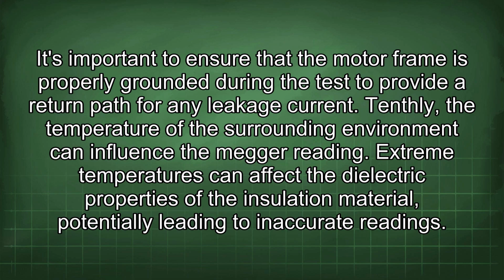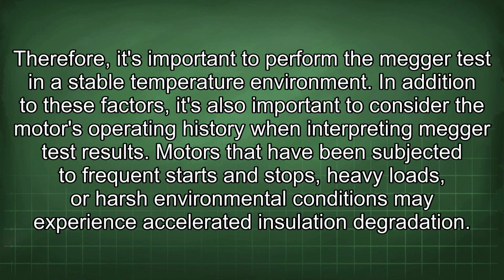Extreme temperatures can affect the dielectric properties of the insulation material, potentially leading to inaccurate readings. Therefore, it's important to perform the Megger test in a stable temperature environment. In addition to these factors, it's also important to consider the motor's operating history when interpreting Megger test results.